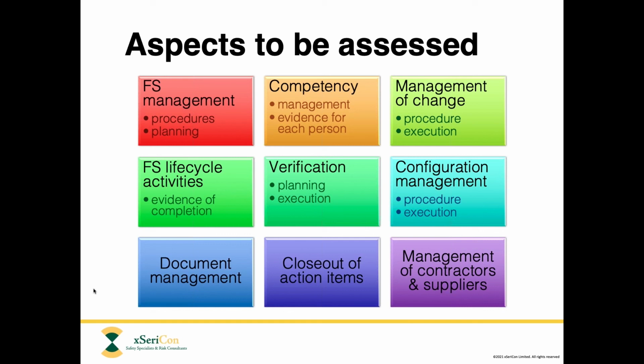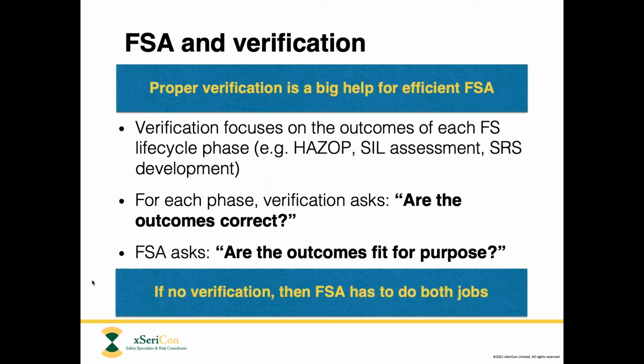Now, I did mention a moment ago that verification and FSA go hand in hand. And if you have not completed a verification of each life cycle phase before going into functional safety assessment for those phases, then FSA is very much more difficult to achieve. And this is why I really wanted to stress at the beginning that it's important to complete all of these assurance or confirmation activities, not just leave it all to the functional safety assessment. If you do that, you will create a big headache for both the assessor and for yourselves.